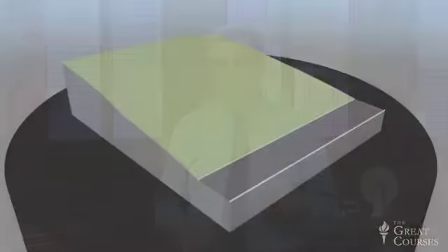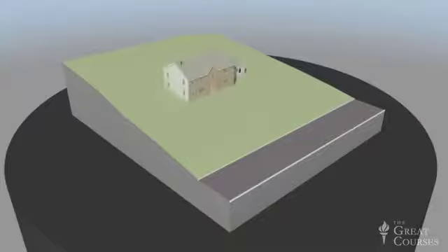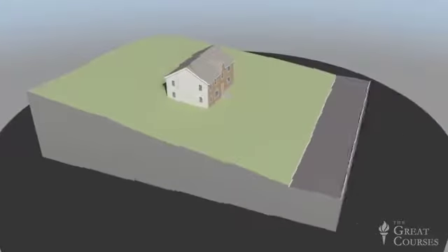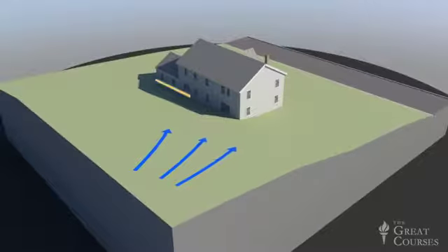To a large extent, this need is fulfilled through earthwork, also called grading. In general terms, grading reforms the topographic contours of the project site for compatibility with the intended land use. This model shows the natural flow of storm runoff across a portion of the undeveloped project site. Now let's add a house. And note that this building interrupts the natural pattern of flow, causing water to accumulate at these two uphill walls, and almost inevitably leading to water infiltration problems.